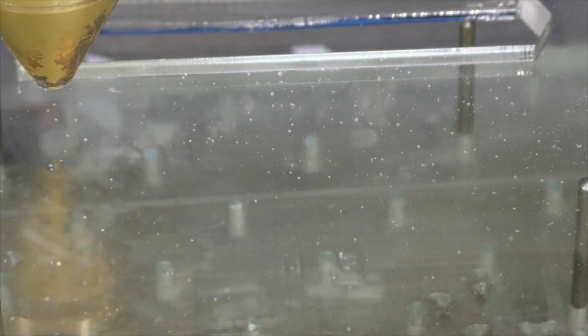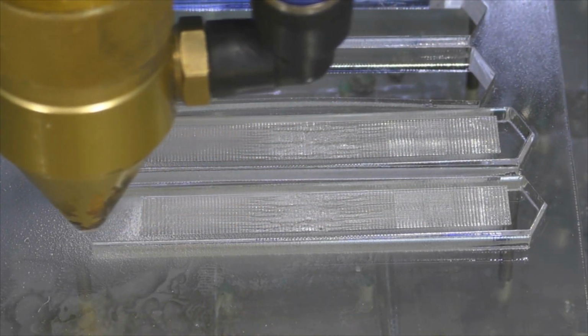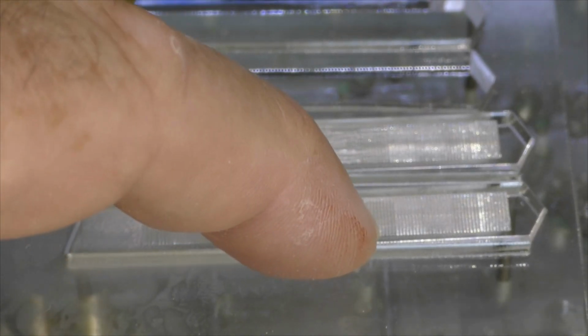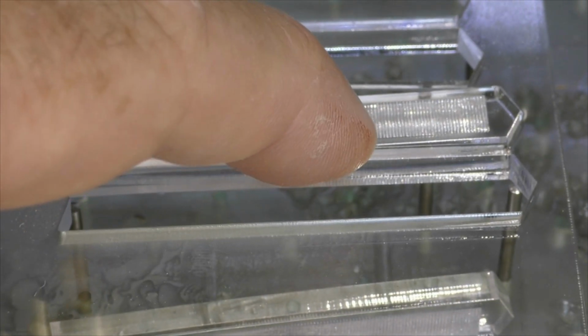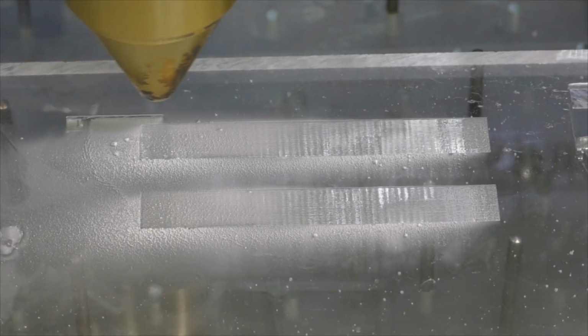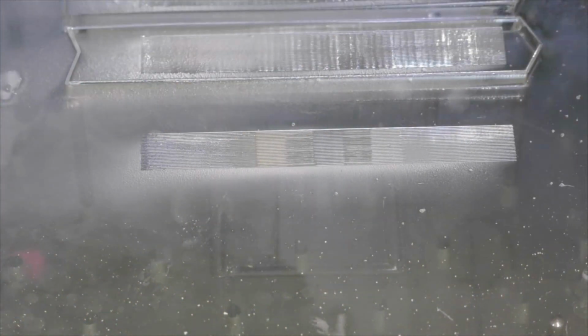Now I'm going to run the same tests again, but this time I'm going to put the speed up to 50 millimeters a second for both of them. The bits aren't falling out because they're so hot on the edge, they're sticky, but I need that to get a nice polished finish. But as you can see, they do actually fall out. They've just very slightly got stuck in there. Now we're doing 200 millimeters a second. And I suppose while we're here, why not? We may as well go for 400 millimeters a second as well. Look at the way the debris is being shot out.